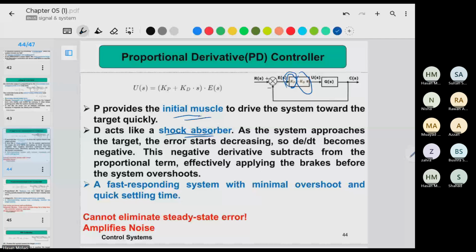And playing with this, you can actually control overshoot while you are still having a fast rise time. And this also helps with the noise problem, because this KP proportional path kind of controls the noise generated by this.